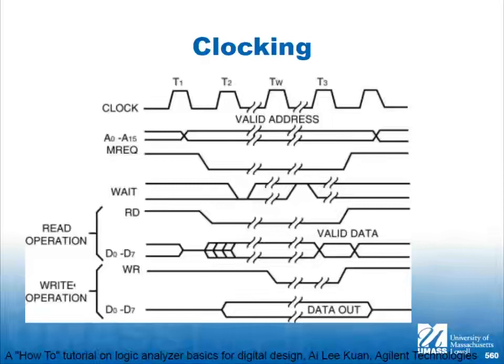Now, what logic analyzers have, and this is the difference between a scope time base and a logic analyzer time base, is that on a logic analyzer, I can use an external clock as my time base. So that means I only have to take 1 sample per clock cycle, or maybe 2. Some allow me to have a rising edge and a falling edge sampling clock, but suffice it to say that it's both more accurate and more efficient in memory.